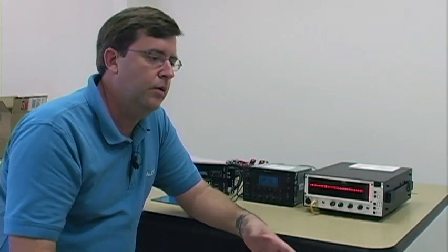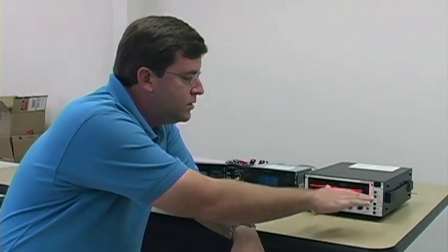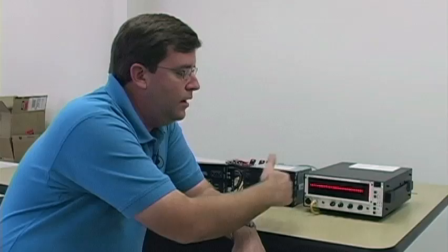From there, we do things in the system to season the response to what we want to hear in the car. We may lift the bass a little bit, brighten up the tweeters, maybe with a passive crossover, maybe with a tone control. But we always want to start with a flat frequency response. That is the purpose of a source unit, really, to provide that flat starting point. If we have any variation in that, it will affect the way our speakers sound in the car.